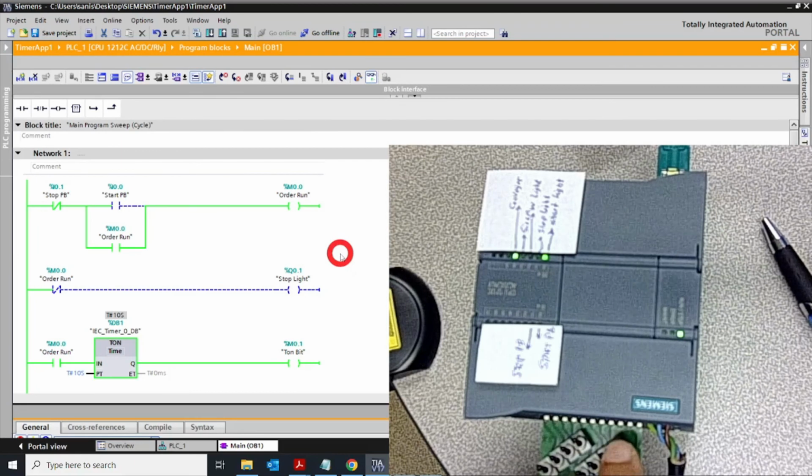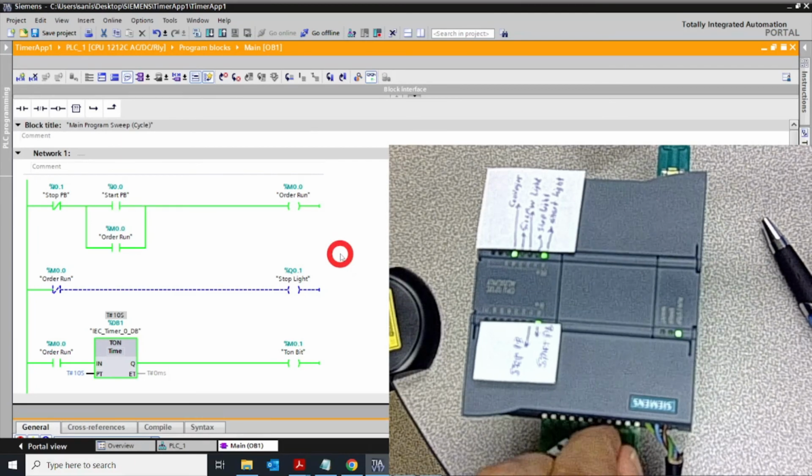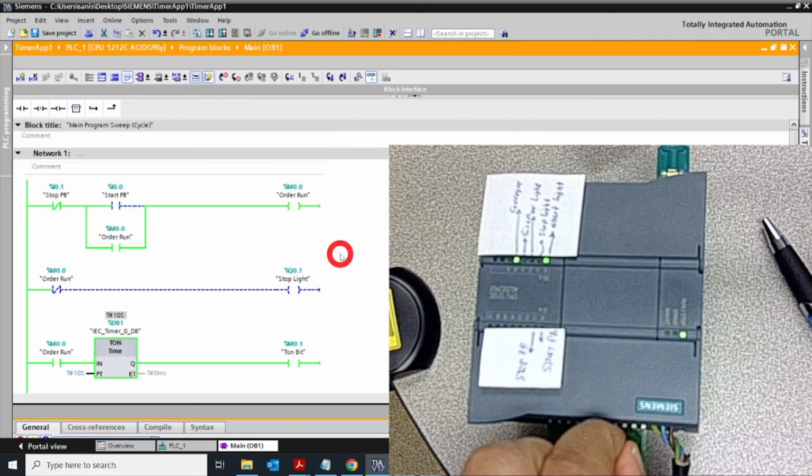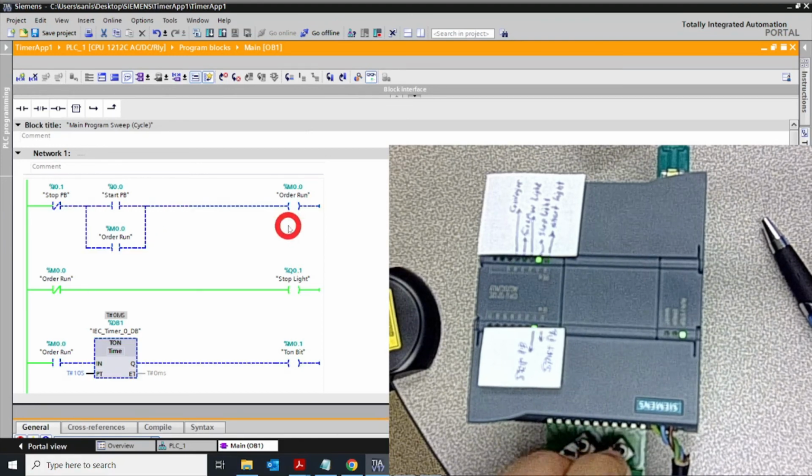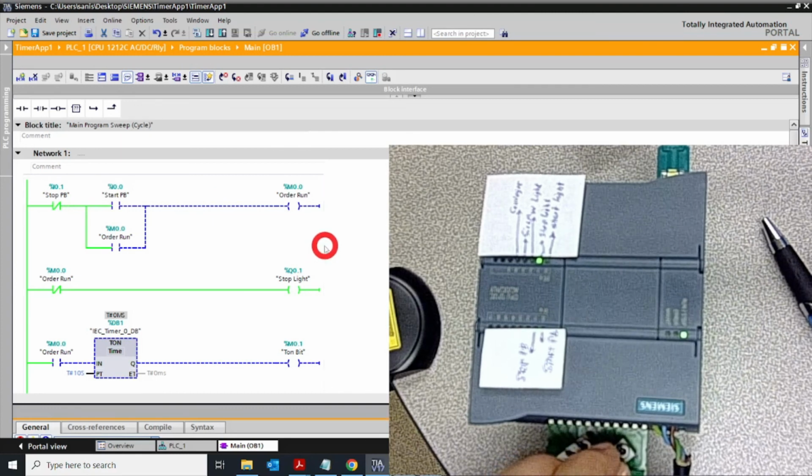Now you see these on. Even while this is working, if I push the start button, it's not actually doing anything. Okay, this is based on the 3-wire circuit that we have. So even though this is off, because of this, your conveyor is actually on and it's working. So let me check that for the last time. We put this stop, and it actually stops.